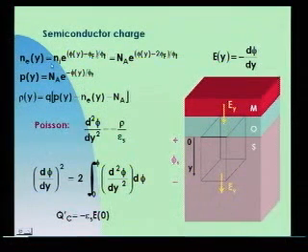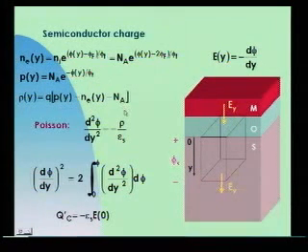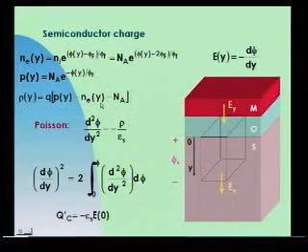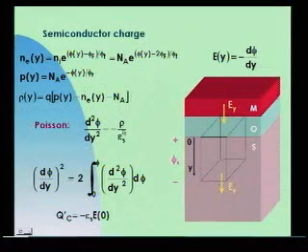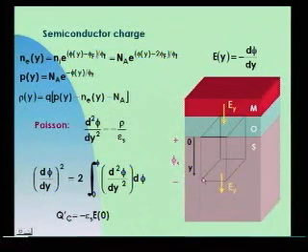So we have for the free electrons this concentration, for the holes, and for the acceptor ions, I have this concentration. We sum all of them. These ones give negative charge, this one positive charge, and this will be substituted here, and then I will integrate this equation to have the electric field in the vertical direction.